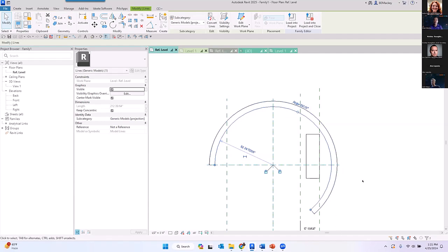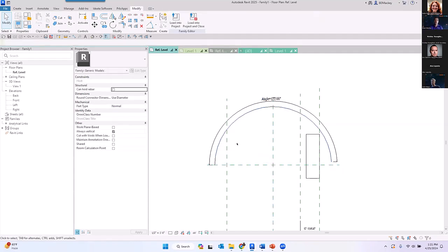As I go through and do this, this is how I've always done my doors. I've never had a door break at a 180-degree angle, or in this case, a 230-degree angle. My doors are always going to be fine with whatever value I decide to put inside of there. So this is one of those things too, that angular constraint, constraining a beginning point.